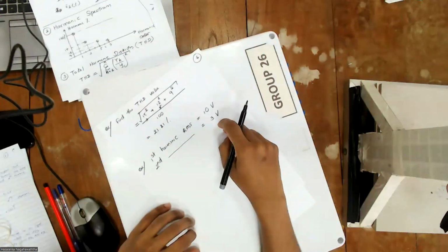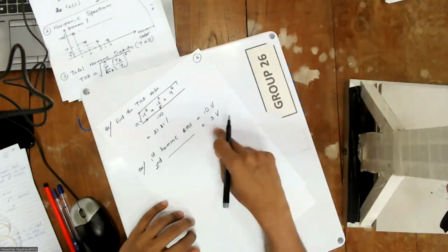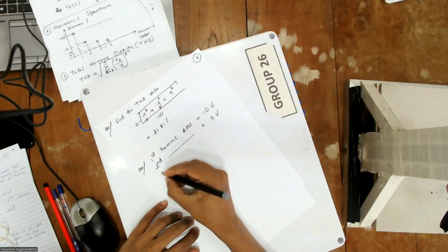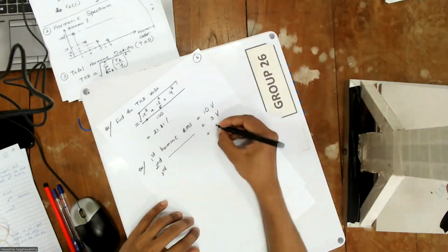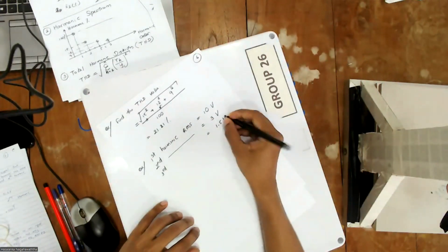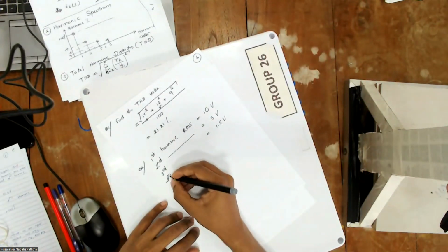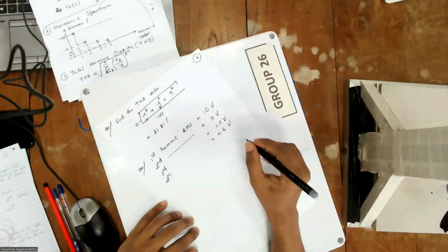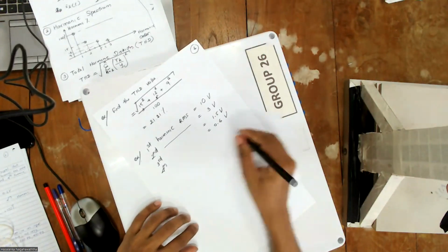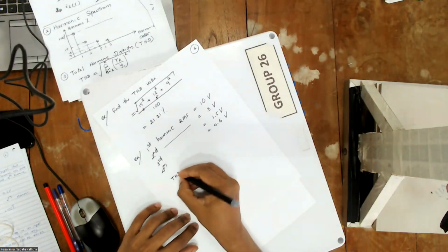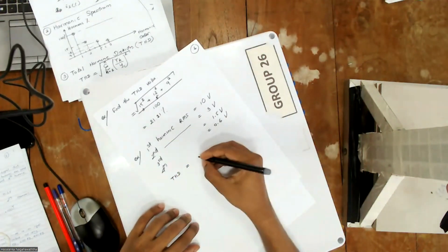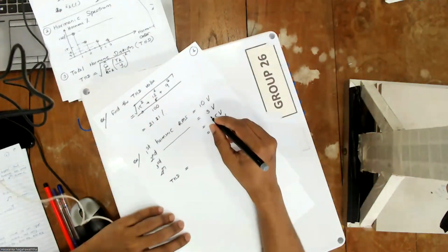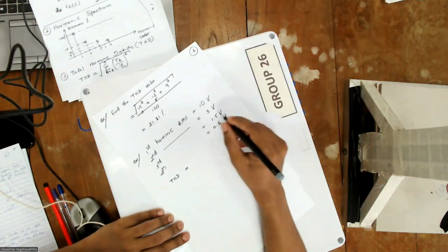Then the second harmonic RMS value is 3 volt, the third harmonic RMS value is 1.5 volt, and the fourth harmonic value is 0.6 volt. Then you can find THD. Since this is given as RMS value, you need no conversion of amplitude to RMS.